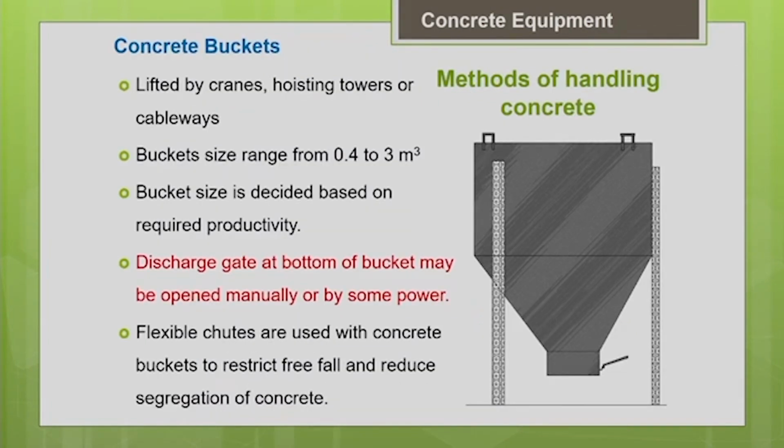So, next is about the concrete buckets. Very commonly we use these concrete buckets lifted by crane, particularly for high rise buildings. You can see that the cranes are used to lift the concrete buckets to the particular floor level to do the concreting work. Not only the cranes, we can also make use of hoisting towers, or you can even use a cable way, as I told you, depending upon the job site location. We can use any lifting device, and with the help of the concrete bucket you can reach the particular height needed.